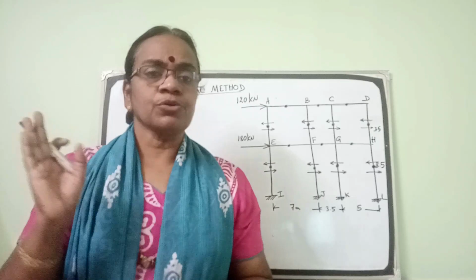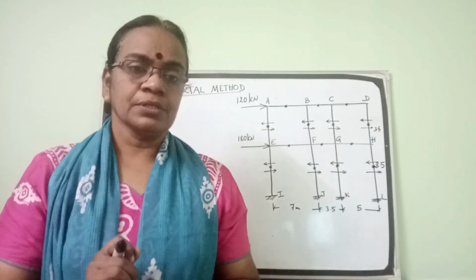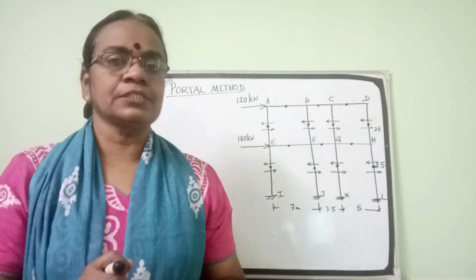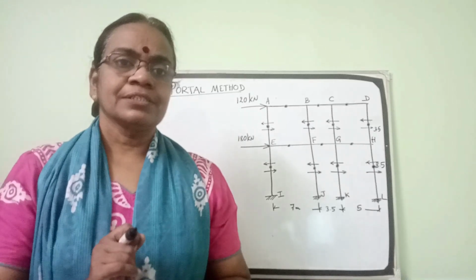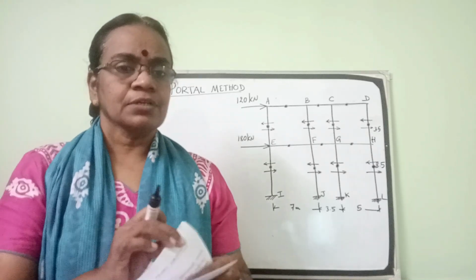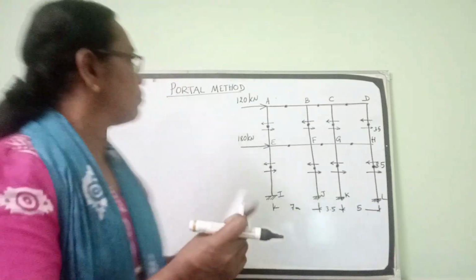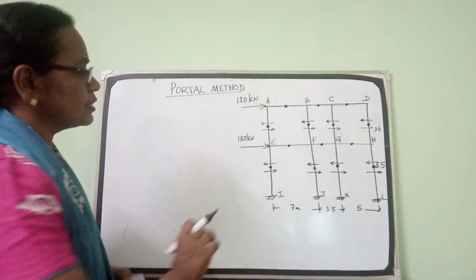And for the horizontal loads, that is wind load and earthquake load, we have three different methods of analysis: portal method, cantilever method and factor method. Of that we are going to discuss the portal method today. So the portal method, let us consider with an example.